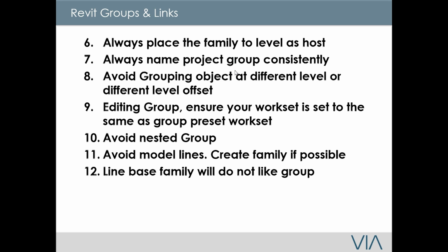So it's always a good idea, if you're doing groups, to stick to one level and not multiple levels, because the more levels you have within a group, the more headache you're going to have, especially when you're doing repeating elements. But if you are doing just a one-off, then I don't mind if you do it. Just keep in mind that for anything repeating, try not to have it.